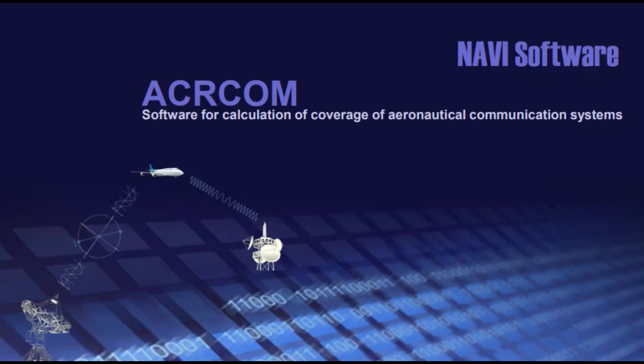For some years I have been developing the Acrcom program. I use the IF77 model to estimate the coverage of the range of a radio station. The Acrcom program results in a coverage radius based on parameters such as transmission power, frequency, minimum reception power level of the aircraft communications equipment, geographic environment, aircraft flight height and various other technical data. The coverage radius allows us to draw a circle within which there will be a reception power level that allows consistent communication between ground station and aircraft.